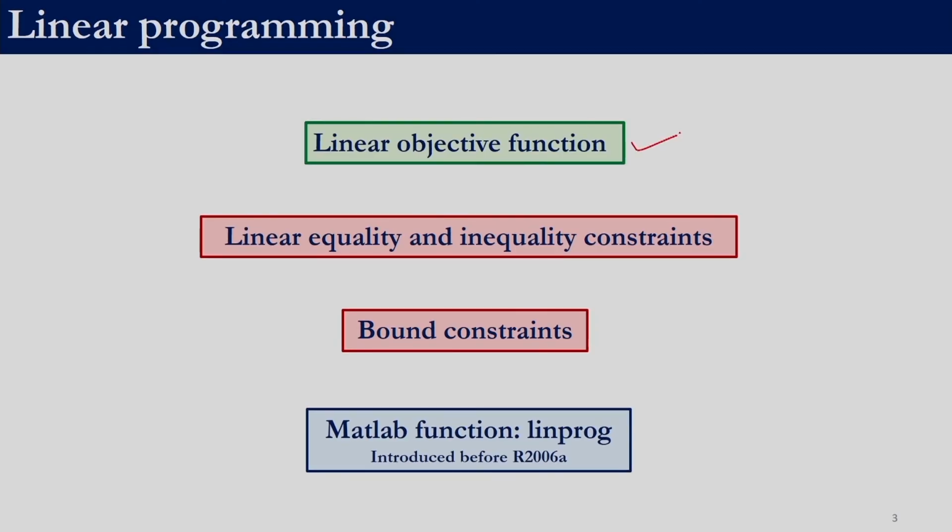To begin with, we will discuss linprog and intlinprog. In this session, we will be looking at how to solve linear programming problems using MATLAB. When we say linear programming problem, the objective function has to be linear. There can be equality as well as inequality constraints, but they need to be linear. Similarly, there can be bound constraints, as in the decision variables are restricted between a lower bound and an upper bound. The MATLAB function to solve a linear programming problem is linprog. linprog has been there in MATLAB for quite some time.